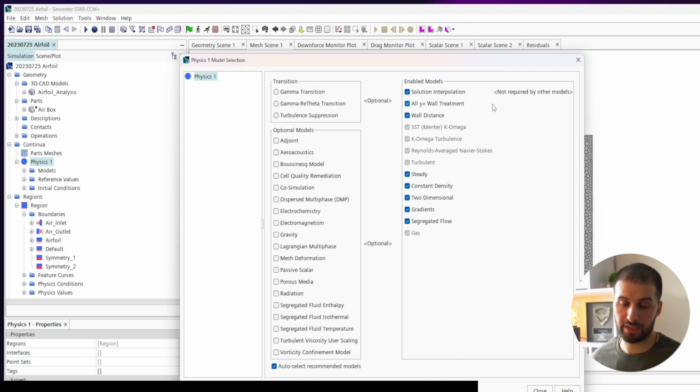Next, model stability and convergence. For complex flows in geometry, the K omega model can offer better stability and convergence behavior than the K epsilon model in general. I'm not talking about all scenarios, but very generally. Stability and convergence, as you will learn, is key to having successful simulations, giving another point in favor of the K omega turbulence model. And if your simulation is not converging, you get a lot of headaches. So looking up best practices on what turbulence model to choose can save you a lot of brain cells and also a lot of sweat and tears.